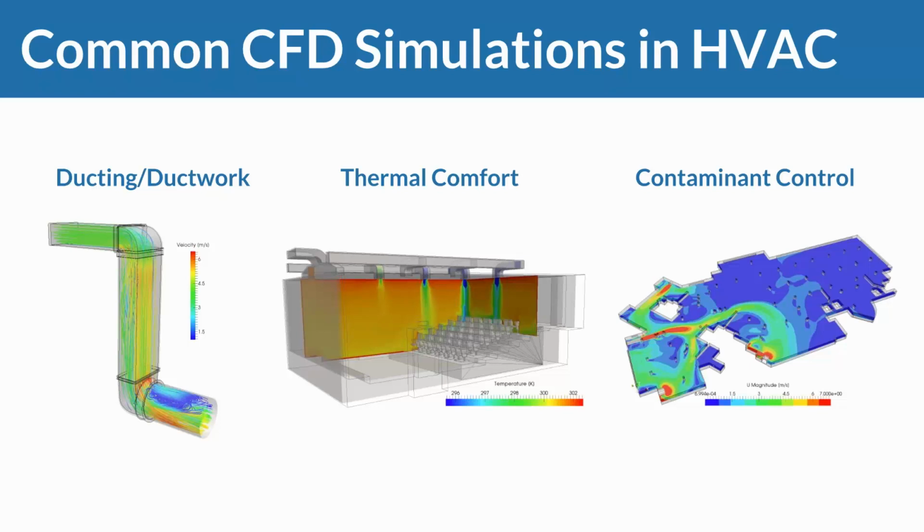But also there are some other interesting building projects where we've seen it happening. For example, when you look at passive ventilation and passive cooling or heating of buildings, where oftentimes you're relying on buoyancy effects of the air to supply fresh air. And there, the pressure drop across ductwork becomes relevant, because if the pressure drop is too high, it's probably not going to work with passive ventilation. So you're going to need mechanical ventilation, which again will require energy, right? Energy consumption. So these are things where we see customers care about simulation for ductwork.